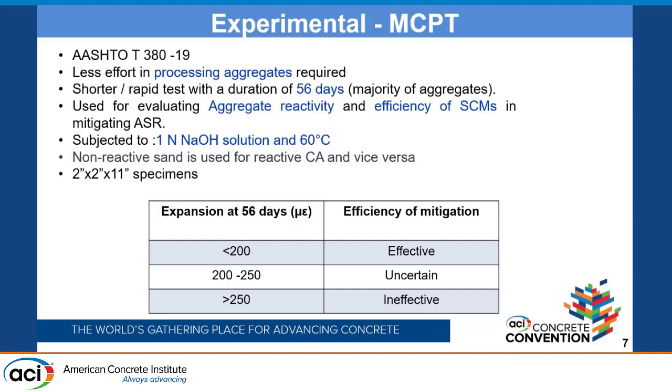One such is the less effort in processing aggregates, and the shorter test duration it offers of 56 days for the majority of aggregates. It is used for evaluation of both aggregate reactivity and efficiency of SCMs. In our case, we are using it to evaluate the efficiency of alkali-activated concretes in this same environment. The conditioning is 1 N NaOH solution, and the storage temperature is 60 degrees Celsius. The specimens that we cast are 2 inch by 2 inch by 11 inches. We use a non-reactive sand for a reactive coarse aggregate and vice versa.